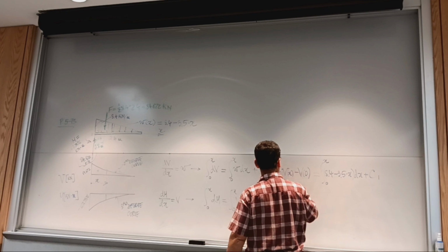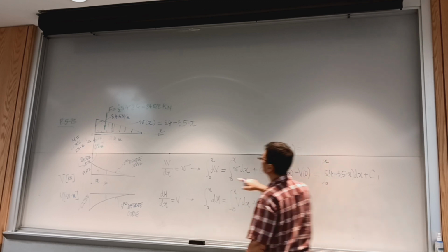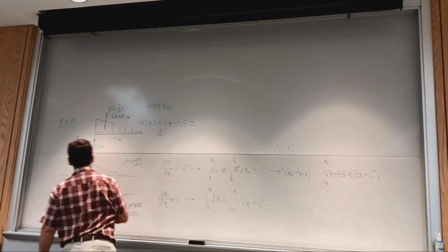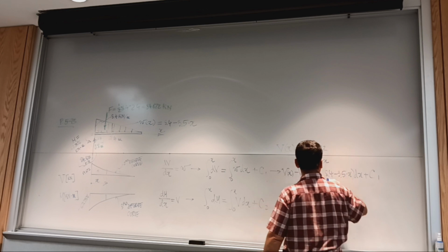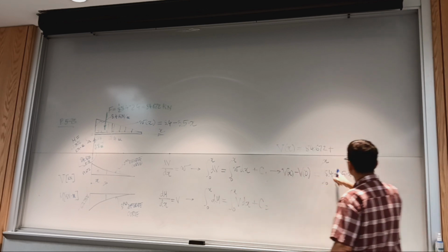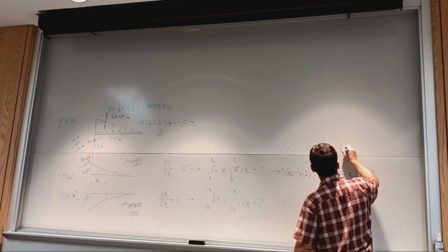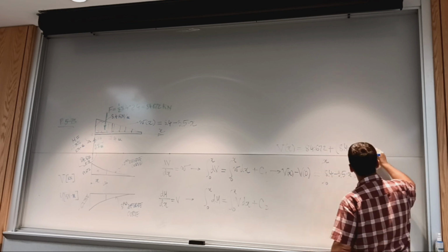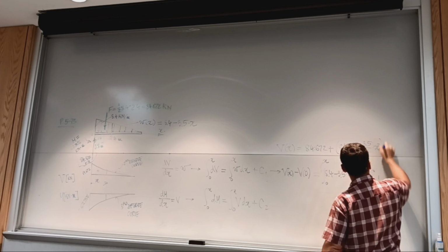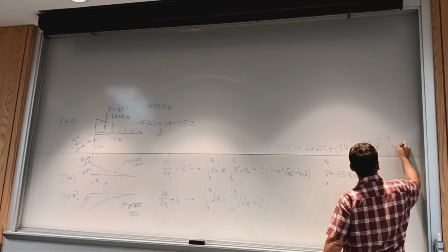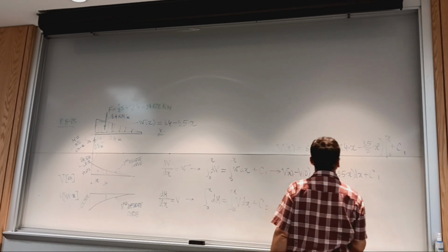So I'm interested in V of x. Let me write above. V of x is going to be 84.672, so I move this to the right, and then I have plus 8.4 times x minus 3.5 divided by 2 times x squared going from 0 to x, plus the constant of integration, C1. So again, I'm moving up with my analysis.